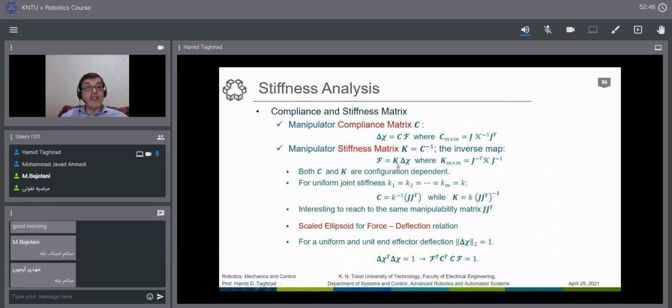As the norm of K gets larger, let's say 10 to the power 6 or something, then the robot is much more stiff, and we can consider it like a rigid robot. But if it is low, if it is 10 to the power 2 or something like that, then the robot is quite flexible or compliant. Not much mathematics here, but the physical concept is very important.